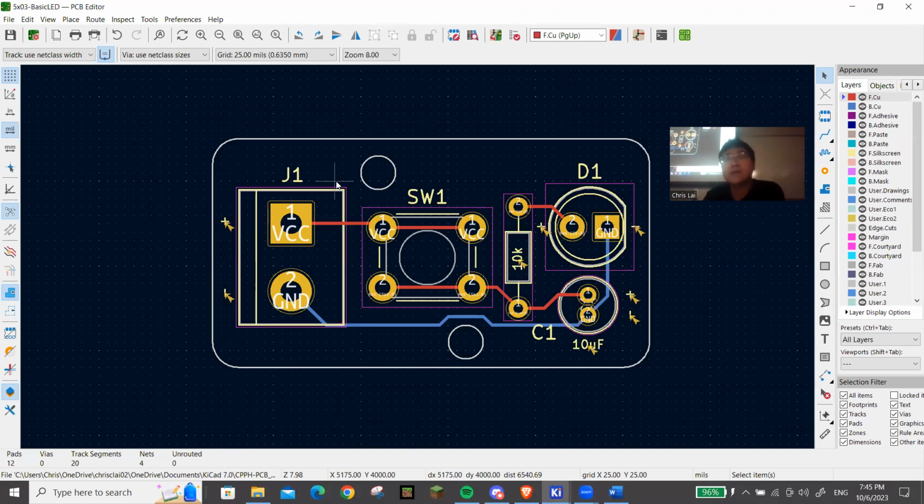All right. Anyone need more time? Yes. Will the trace width affect resistance? Yes. It will affect resistance. It'll affect a lot of things, but generally the reason you would want to change your trace width is you want to allow more current to pass through that route. So for example, if I wanted to build like a solenoid driver, and by the way, a solenoid is like a piston, like a Minecraft piston. Solenoids use a lot of current. Most of the time there's 3 amps.